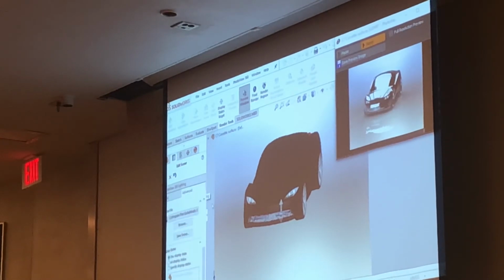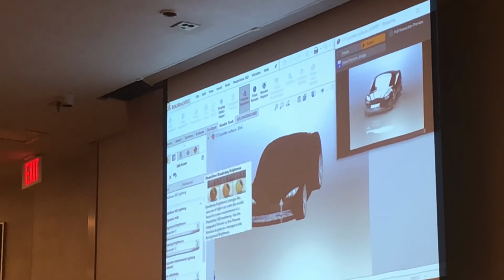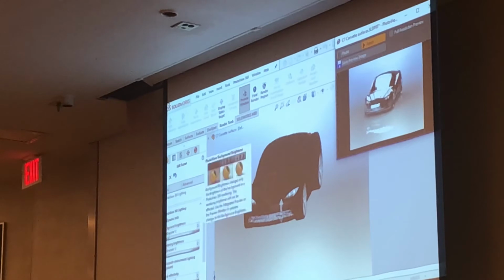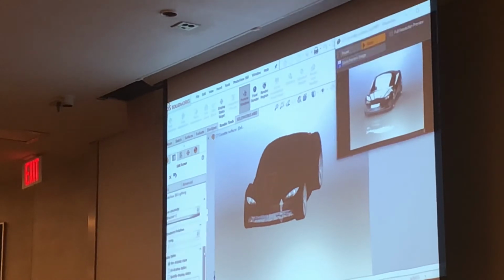And if you go to the Advanced tab, you have options like rotating the environment image. And then on the Lighting tab, you also have options for setting the brightness and the reflectivity. So if you wanted the car to look like it was all chromed out, you could increase the reflectivity setting. If you wanted it to look more faded and kind of washed out, you could play around with the brightness and things like that. I'll just accept that for now.